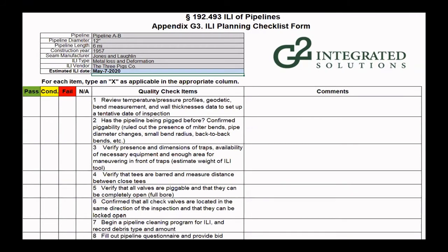If you have 1D or you have 3D or even less, you will need to choose carefully the inline inspection tool and make sure that you are using the correct tool. Especially field bends and river crossings must be reviewed thoroughly because some pipelines could contain tight radius bends and even miter bends.